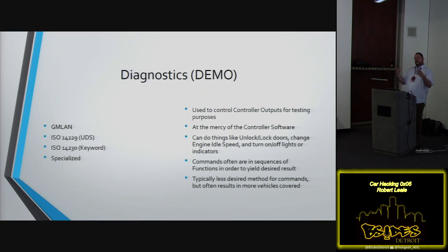They allow you to just read the memory out of the controller. I use that a lot for reverse engineering, to see maybe there's a switch in memory, or maybe a secret key for something that might be interesting for use later, like secret keys, maybe security algorithms, all that fun stuff.